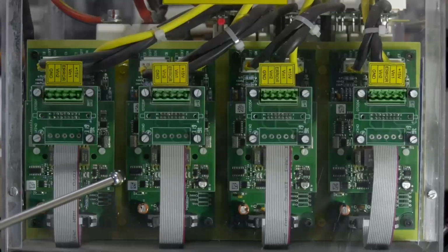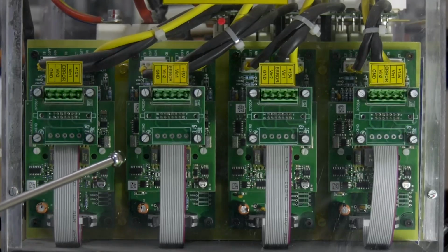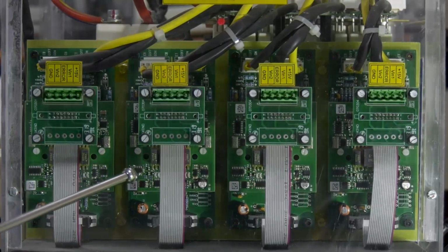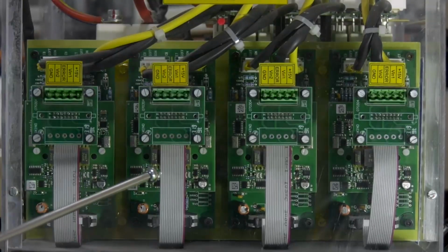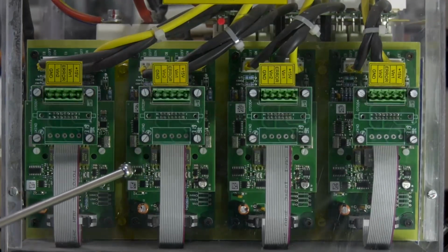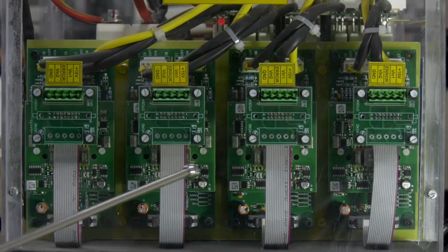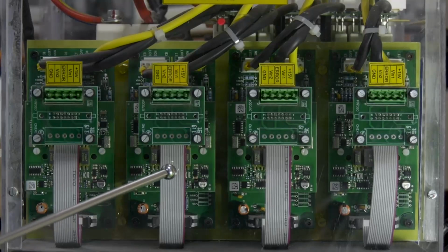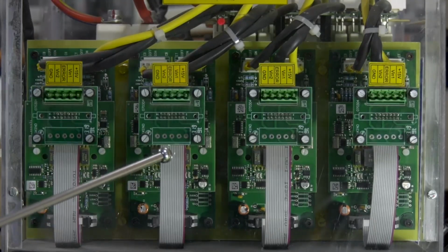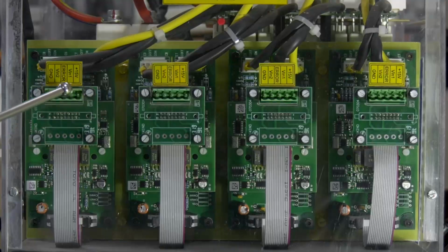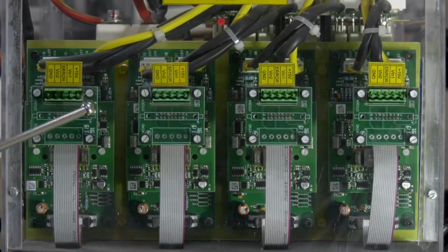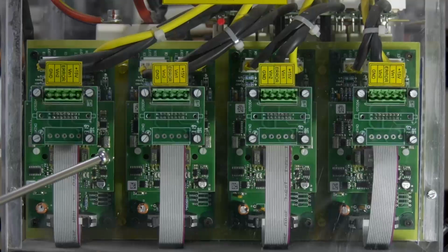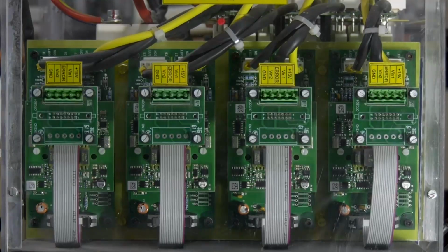To trigger the IGBT switches, gate drivers are required to convey the pulses received from the controller to the gate terminal of the IGBT. Each driver can trigger one module. Hence, 4 Skyper 32R gate drivers are provided, and these drivers also require an isolated DC input of plus or minus 15 volts to operate. Moreover, these drivers have inbuilt dead band protection as well.